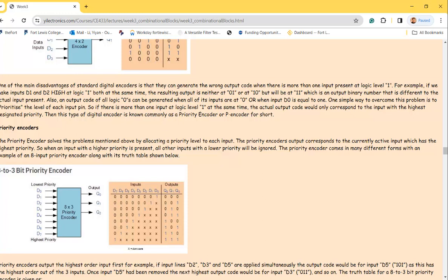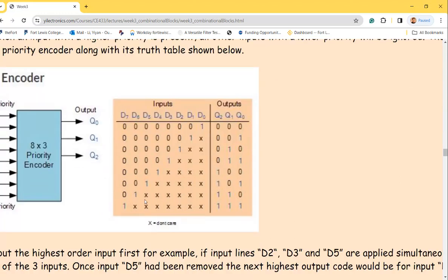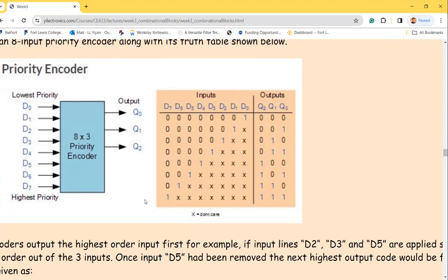Okay, it's called priority encoders. So how do you list all the possibilities? Have you learned the don't cares in the truth table? Don't cares is just placing the little cross over here, so it actually covers both cases. Don't care is when you are writing down that logic expression, you just don't care about it. So whenever one of the bits is getting flipped, for example in this case, whenever this one is flipped, then you definitely are outputting this certain result. Same for the second row.